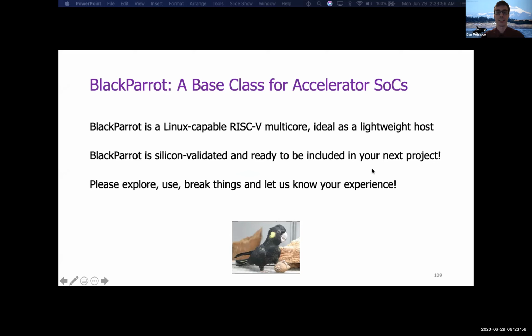Sure. Yeah, that's a great question. It really comes down to complexity. First, the Bedrock network with its 3 networks has a static prioritization scheme between the 3 channels. So you're able to guarantee that you're deadlock free as long as you follow these very simple protocols.